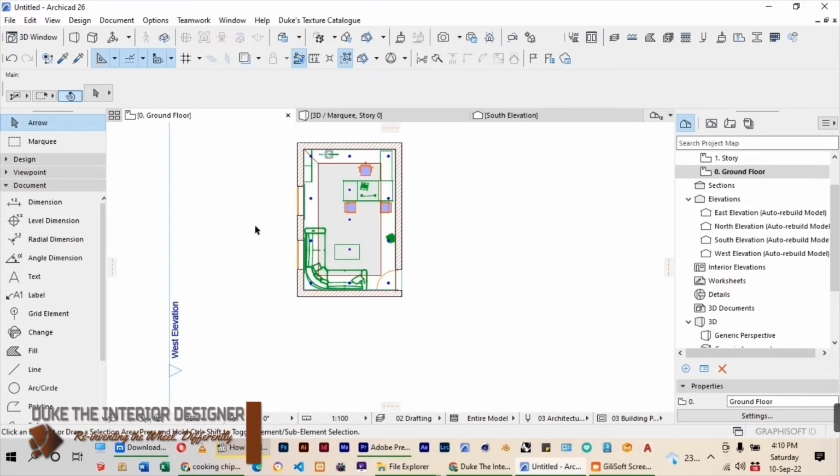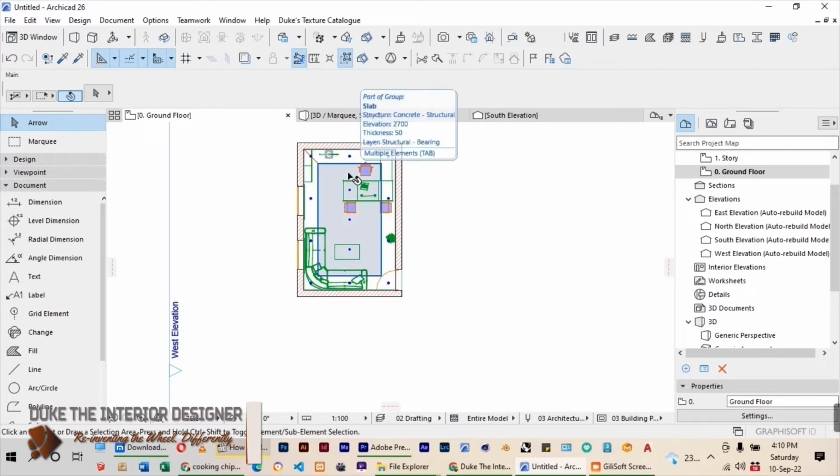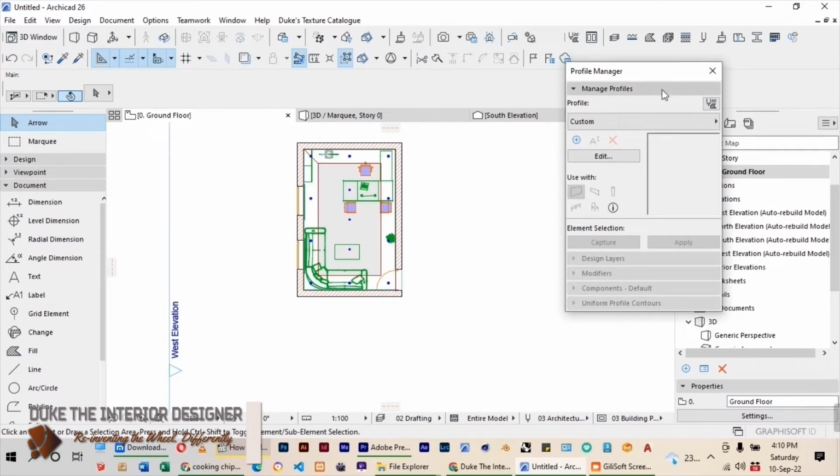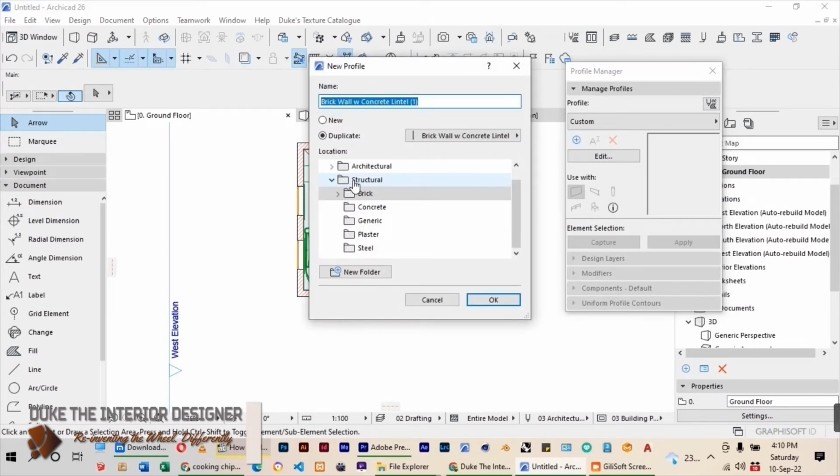Now the next big step is putting the textures. It's very important to have very nice textures. Before I forget, we also need to do what we call a cornice for the edge. A cornice is normally put between the wall and the ceiling. I'll go to Profile, click on New. I'll still do under Structure. Let me first go to New and say